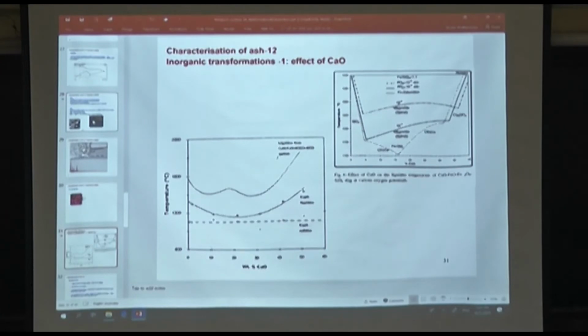So even if you run your combustor or gasifier, judging by the indications given by your thermocouple, that I am operating only around 800 degrees or 850 degrees, that may not be right. Somehow the particles have experienced very high temperature and that has given rise to this.